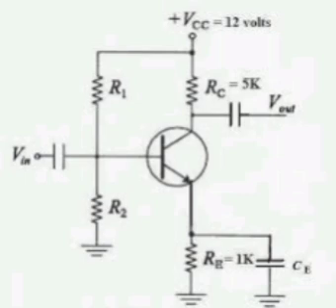Then V1 means I1, so the input transformer n:1 comes in. Input current I1, output current I2, V1 and V2 windings. V2 by V1 equals 1 by n, I1 by I2 equals minus 1 by n. V1 equals n V2, I1 equals minus 1 by n I2. ABCD equals n, 0, 0, 1 by n. Two cascaded networks: ABCD of 1 plus YZ, Z, Y, 1 multiplied with n, 0, 0, 1 by n. ABCD means n into 1 plus YZ, Z by n, nY, 1 by n. That is about the ABCD parameters.